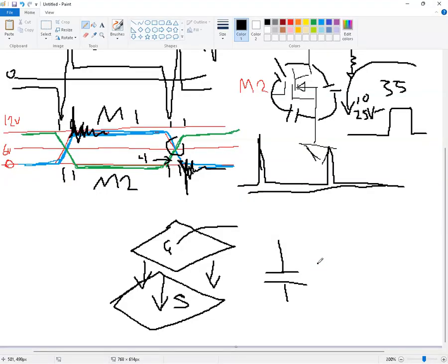When you charge it with a square wave, it coming on and remaining on is not a problem. The problem is this capacitor takes time to charge. This is where the current occurs in charging a gate. How fast you can charge this is where you're taking the current. So the faster the frequency, the more current it pulls. That is a serious thing, more current.